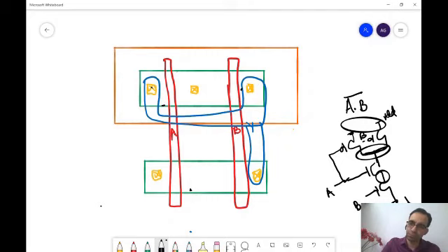But the diffusion capacitance was the sum of the source, right? You said total diffusion capacitance. Did I say sum of source and drain capacitance? We only looked at one capacitance. We said whether it is source or drain, this is how you should calculate the capacitance. It was the sum of two components, but what were those two components? Again, this is a hint. One was the width and the other was the length, LS.